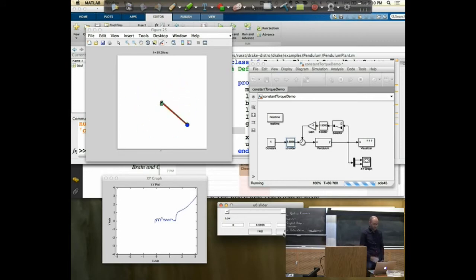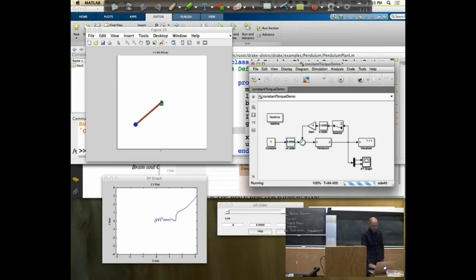Just for grins, the real pendulum when I did the demo had additional details, right? In this model it was easy for me to set the friction to 0. The real system had friction. I had to model that friction with a quick experiment before I came down and invert it, so I had a feedback cancellation that was taking out friction. The friction changed a little bit as it went to higher speed. So basically, I was even adding energy every time, and it was wild. It was awesome. But now it's safe.